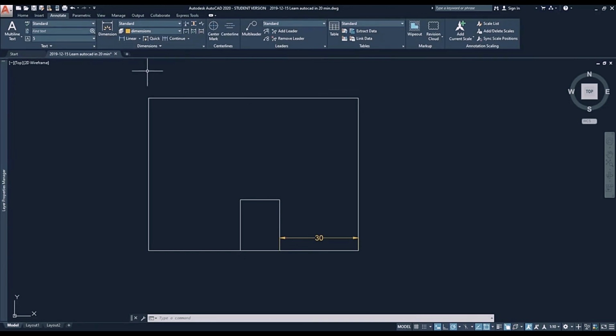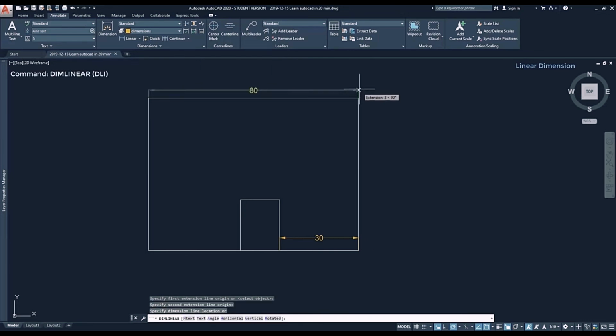So there are several types of dimension lines, which you can find by clicking on this arrow. For now, let's start with the most common one, linear dimension. To insert a dimension line, I just click on 2 points. Then I click again to put the dimension line in the place that I want. So it's very simple. However, this feature is quite complex and we usually have to set up some settings. Sometimes the dimension lines are not proportional with the sizes of the objects that they measure.